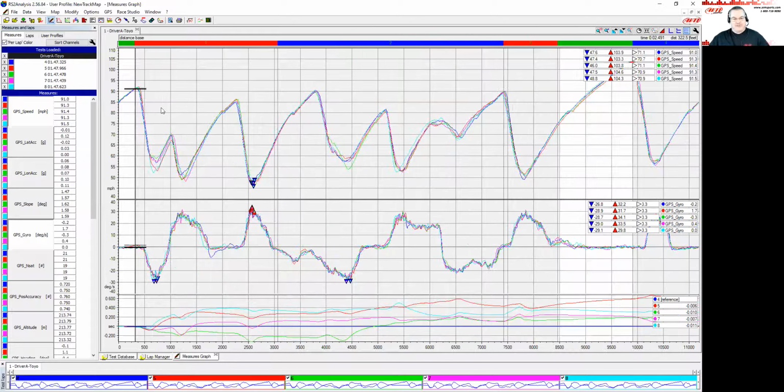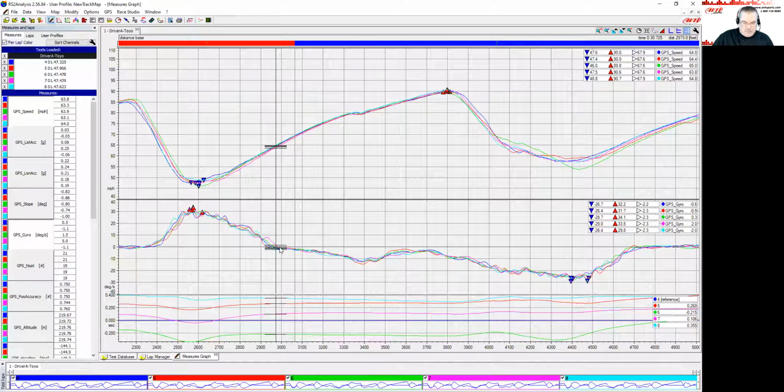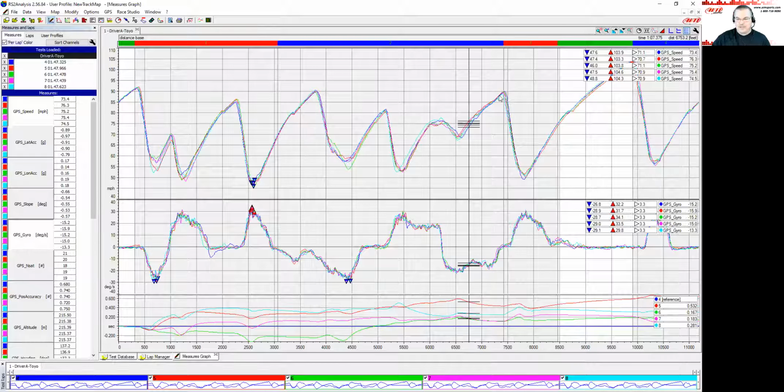Then you go around and maybe you wanted one here where this transition happened. Now I can see exactly when that happened. I can zoom in a little bit. And if I want to stay away from this last little bit of the transition, I could come to there maybe, and it's 3025, let's say, right? And just walk our way around the lap of where we want to be even more specific, because we have multiple laps up. We can see what we did in a bunch of laps. If we want to do this braking zone, we could pull it back. I tend to round a little bit, but maybe it's 3770. Write them down as you walk your way around the entire track by clicking where you might want.